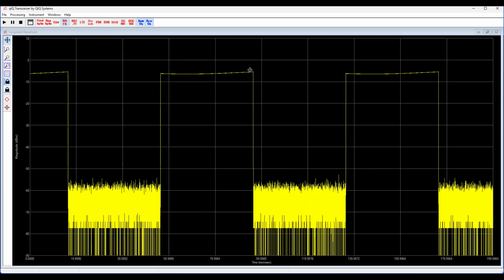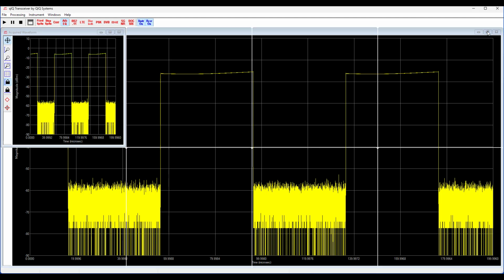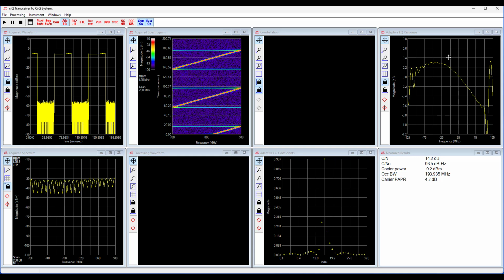You'll notice that it tends to go down maybe a little bit and then swing up at the higher frequency end of things. The response of our system is not flat. It's got a little bit of character to it. And so what the adaptive equalization is trying to do is to come up with a filter that's going to compensate for the imperfections in our system. And in this case, we're only looking at the magnitude, but it would also be doing that in phase.